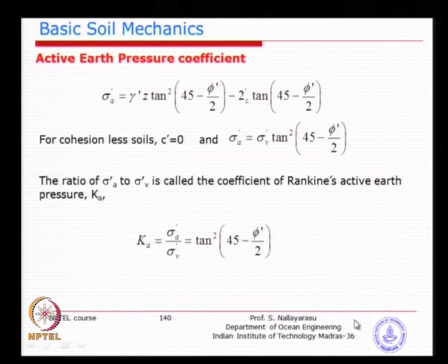That is why we need to know what will be the pressure put forward by a vertical pressure applied from the foundation and superstructure to the soil in the horizontal direction. This relationship is very important, because all along, whether it is a pile foundation design or shallow footing design or any type of foundation, this will be very, very important, because that is the relationship we will be using to derive several formulas for foundation capacity. So, that is why I was thinking to introduce this.